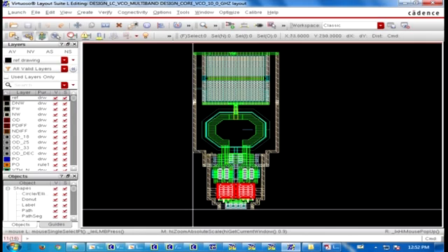Then here are the varicap capacitors, and here the main tuning capacitance, and there is the switching. The switch is a digital type of thing and is not required to be close, so you can put it some distance from that inductor or capacitor. PMOS cross coupled is not here, NMOS cross coupled only. And these are the biasing transistors, which give the current to the inductor.